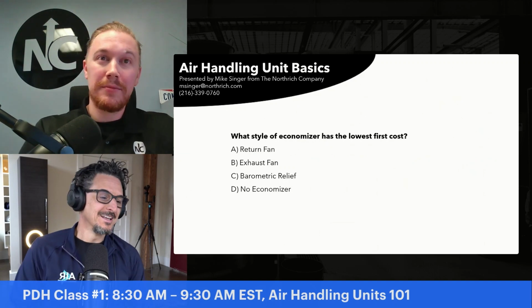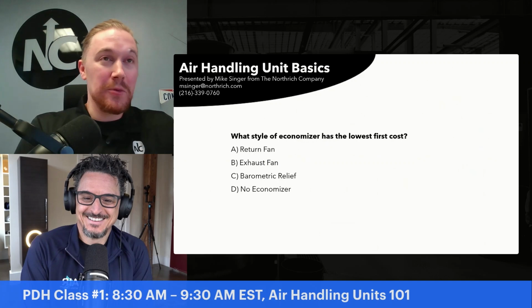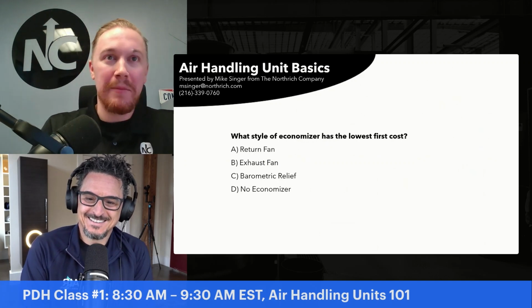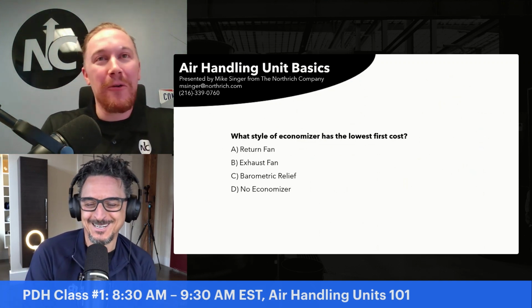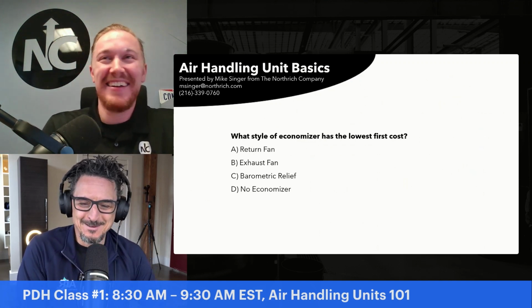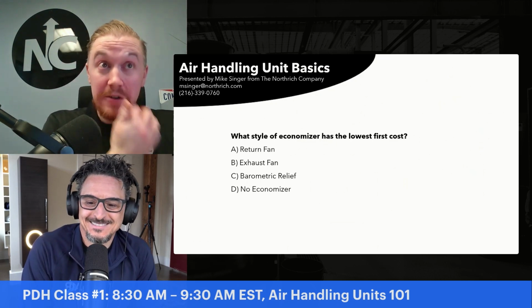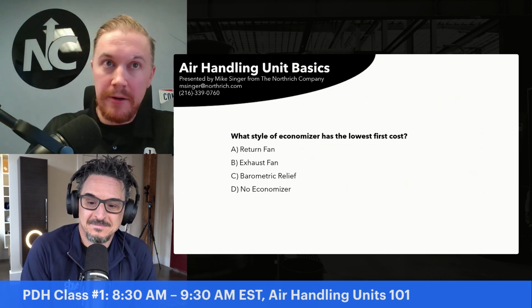Although no economizer would be our cheapest option, if we're looking for an economizer of lowest first cost, barometric relief is going to be the option there.